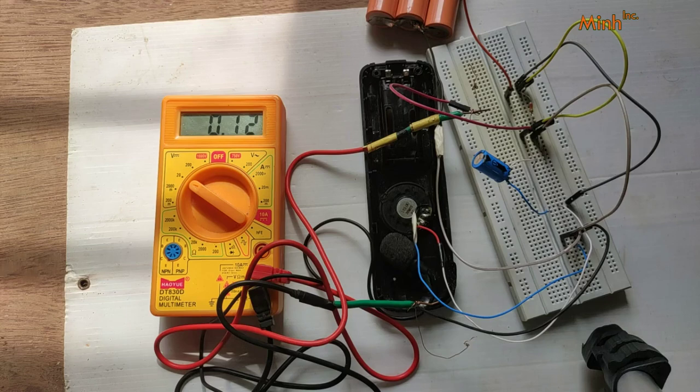So the capacitor is charging. Okay, so the voltage at the base of the NPN transistor reaches more than 0.6 volt and it remains there at that voltage, so it will be active for some time, and then it becomes non-active and it drops. So now voltage is growing, so the circuit is cut off, the capacitor is charging, and okay, it remains there for some time.